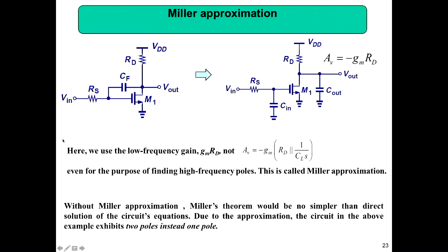Then why is Miller's theorem relevant? Why do we have to take into account the capacitor in your amplifier? Yes, in the amplifier, but maybe the fundamental quantity will be capacitors in the MOS transistor or BJT transistors. This output capacitor may be coming from a load. But this input capacitor may come from between gate and source. And this floating capacitor may be between drain and gate.